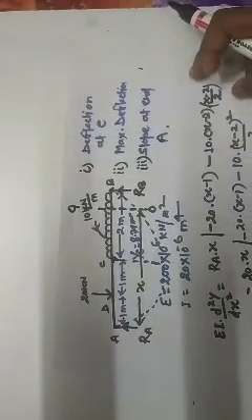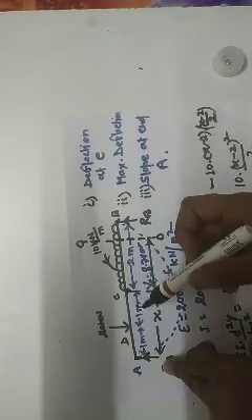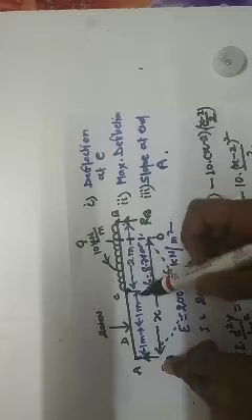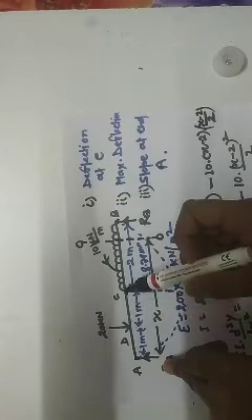Right? Now, next we are required to calculate the maximum deflection, that is, y max. We know that deflection will be maximum when the slope is 0, right? From this figure, we have to judge it by hit and trial, and we will solve a number of problems through a number of examples. Then we will be able to judge by looking at the problem that the maximum deflection will happen in between C and D. Say we are assuming that the maximum deflection is happening in between C and D.